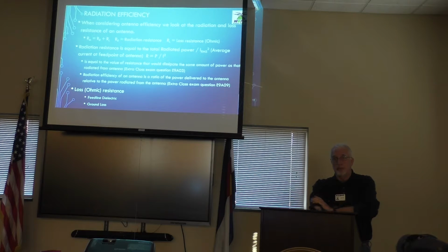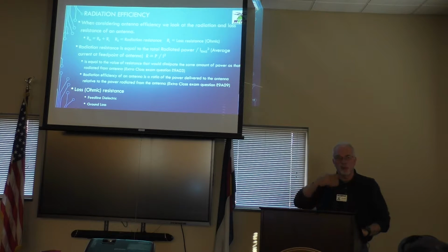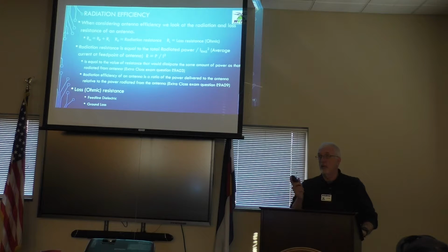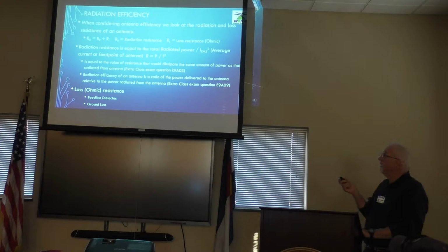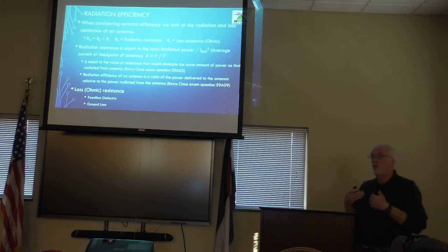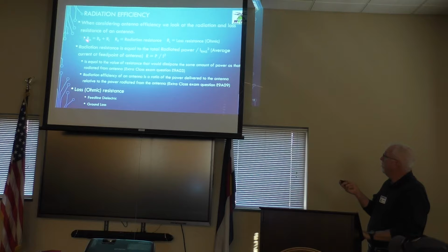Let's talk a little bit about radiation efficiency. By the way, I'm just running through terminology that you will hear or see when you're looking at antennas. Don't feel like you have to remember them, but if you just get a hint of the concept, these are not calculations that you have to do, but it's something to strive for. As it states, radiation efficiency: how well are you putting a signal out into space? That resistance is characterized by the radiation resistance and the loss resistance.